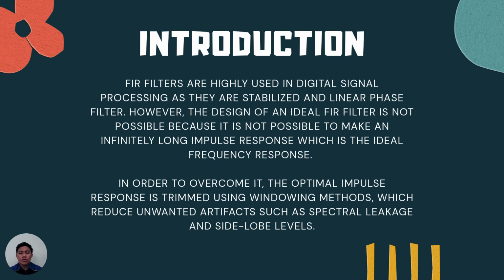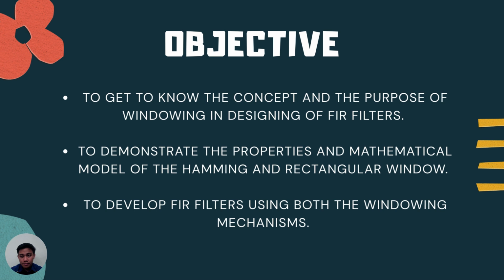In order to overcome it, the optimal impulse response is achieved using the windowing method, which reduces unwanted artifacts such as spectral leakage and side lobe level.